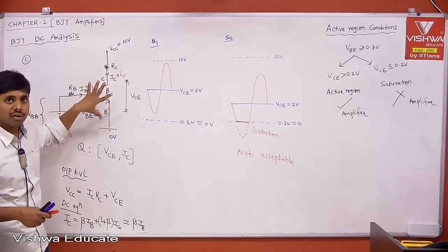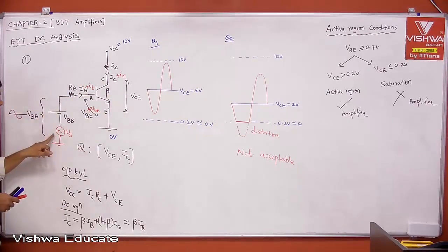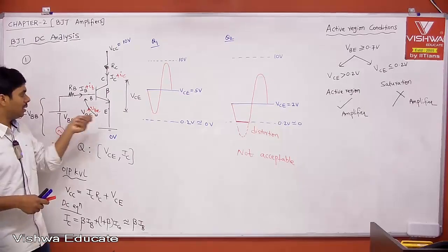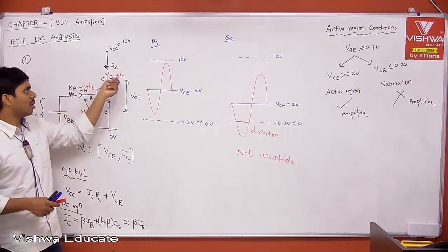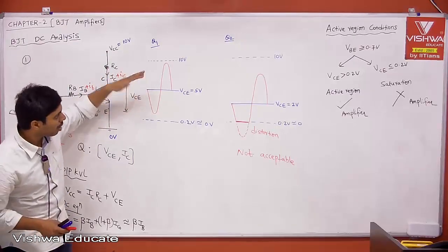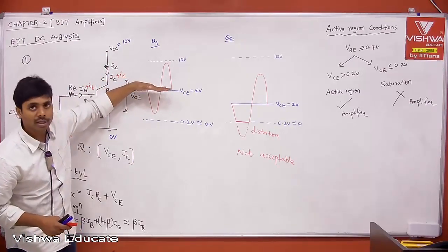When the transistor is ready for amplification, then we apply the AC signal to amplify. Then the small VBE is giving small IB, the small IB is giving small IC, then the drop across RC, and then ultimately the output voltage, which is swinging about the DC voltage. That is what is your operating point.